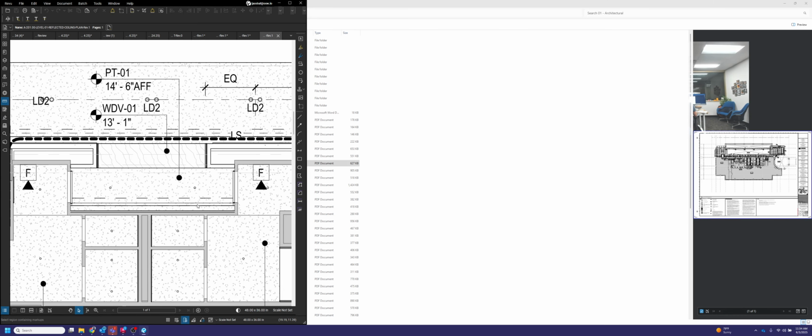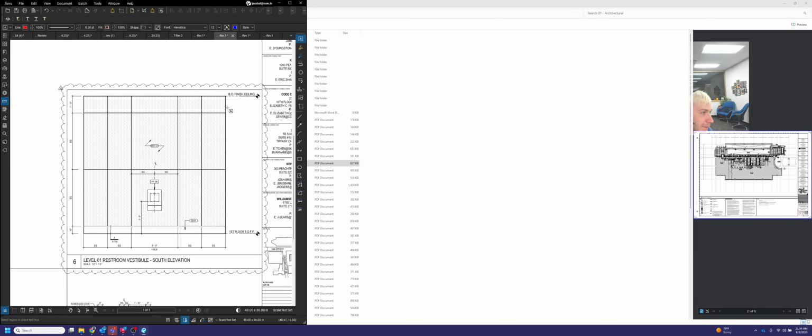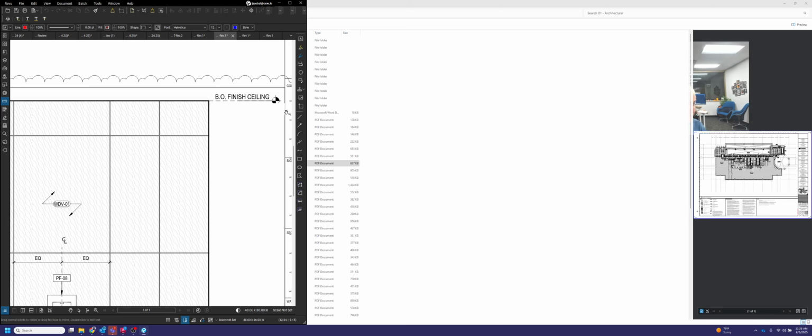Anyways. So the ceiling height in that room is 14'6". So we're going to use that math to our advantage. We're going to go back to our elevation view now that we know that. Make a quick mental note that, let's see, what's 14'6" in inches? That would be 174 inches tall above finished floor.